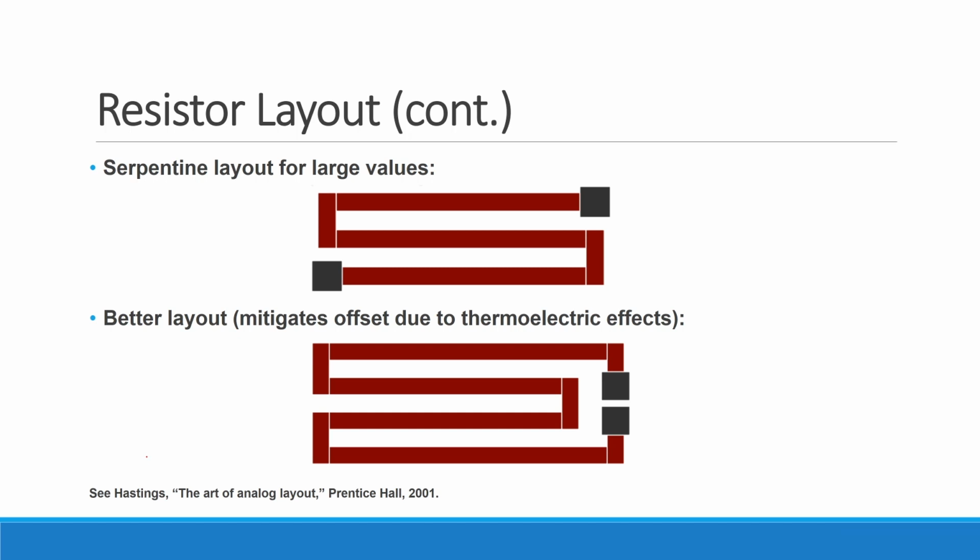These things like basically these so-called serpentine resistors that are symmetric about one point. I'm not going to spend a lot of time talking about it. Bottom line, if you really have to do a really, really precise analog layout, get either this book or something like it and read through it and learn all of the nasty tricks you're going to have to play. Because bottom line, if you really, really care about it, there's all kinds of ways you can screw up. The good news is, again, many people already screwed things up that way, so at least they can tell you, okay, don't repeat this particular screw up.